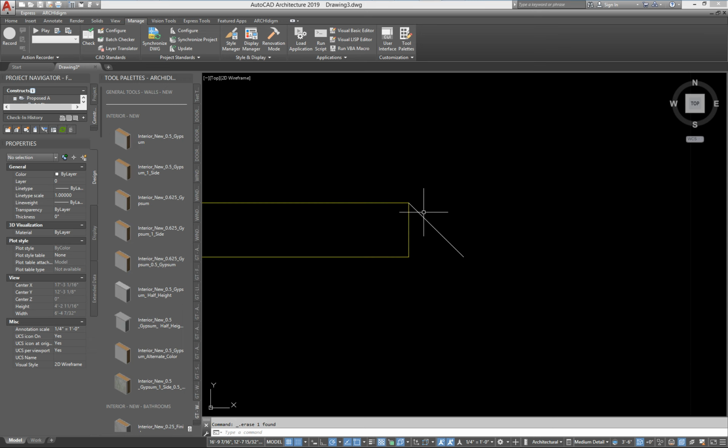Now this won't work right here. If you just draw a line like that and call it an end cap, it won't work. That's just a straight segment. It doesn't understand what you're doing to the two sides of the wall. So it has this corner and that corner, and this doesn't define what those two corners are supposed to do. So I'll move that over here. I could throw it away, but I'll just move it over here as reference. So what it really wants to know is this.